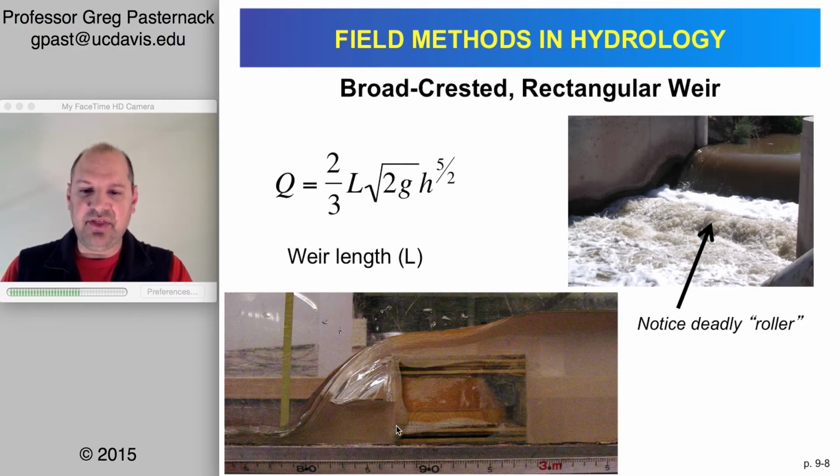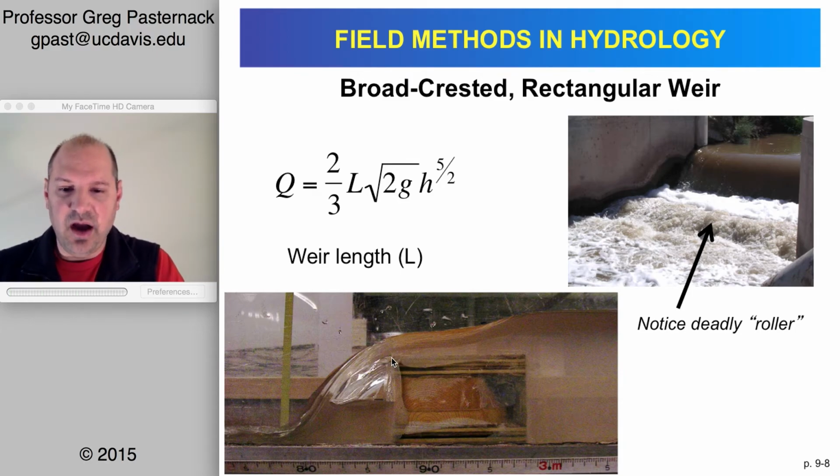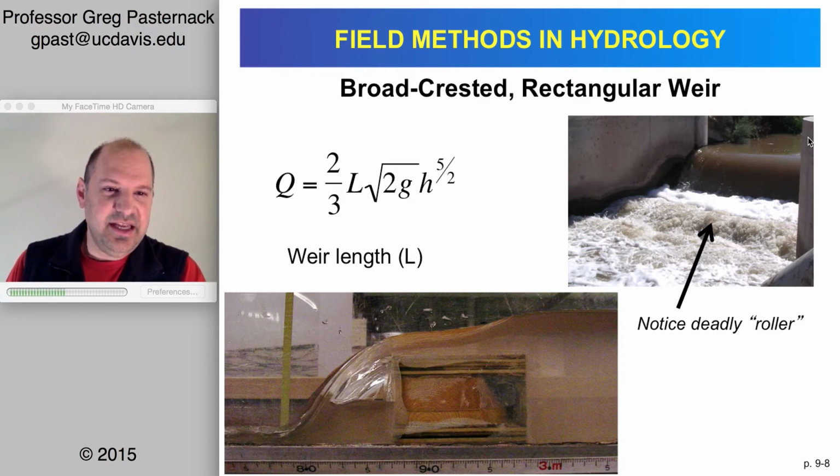If you look in cross-section, it's nothing more than a block filling the river, and what happens is when the water hits this block, it all has to funnel up into this narrow space. And it just turns out, if you study fluid mechanics, that when water is concentrated like that, the water surface doesn't actually bounce up, it gets sucked down. And the water converges as it moves across that broad-crested weir to the brink. And then there's the overflow, and there can be a pool behind that, recirculation as well as downstream. Now this laboratory illustration doesn't show a downstream stilling area, but in this real-world agricultural broad-crested weir, you can see just the perfect symmetry of depth that's represented here.